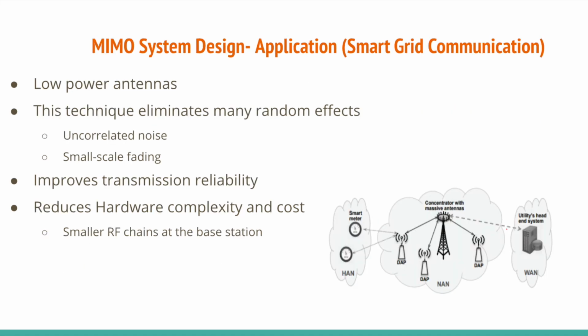To study the impact of this technology, we analyzed several application use cases like the one presented in this slide. It has been shown that space modulation techniques enhance error performance with a moderate number of transmit antennas as compared to other conventional MIMO techniques. In addition, it is demonstrated that these techniques are more robust to channel imperfections, such as spatial channel correlation and channel estimation errors, as compared to other MIMO techniques, since the probability of error of space modulation systems is not determined by the actual channel realization, but rather by the differences between channels associated with the different transmit antennas.